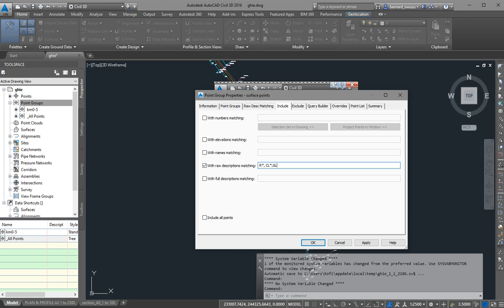GL. Good. The GL too, let's add an asterisk to it. In this particular data, you see there's a point called GLF. That's ground levels that were picked in farms. So I told them to code it GLF. So at least when we are doing the design, we have an idea that there's a farmland here, so you know how to save it and minimize property impact. So GL asterisk. Is that all? I think that is all for now. So just these three, the R, the CL, and GL asterisk.